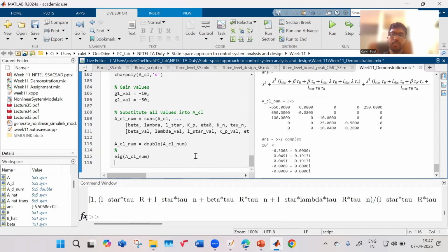So there are certain limitations, like it is not completely state feedback, because we are only having the feedback of some states. We don't have the feedback of all the states, and because of that, we cannot perform arbitrary pole placement. We cannot place all the poles as we desire. Like we cannot control each coefficient of the characteristic polynomial. But there are 2, 3 coefficients which can be controlled by the feedback of 2 states. And we have considered an example with -10, -50, etc., and used that to check whether the system is stable or not. It is found that the system is stable, right?